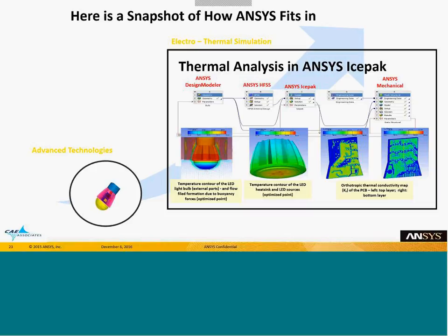Okay, so this was a very non-trivial simulation that we had to do, pulling all our physics together, and we used a platform that we call Workbench. We brought in the geometry. We had to design the antenna element. We used the HFSS design. We had to be cognizant of how the air was flowing inside the unit, inside the housing of that light bulb, as well as the airflow in the room that it was placed in, because not every room is air conditioned, or it could be heated up, and there are different environments. We have to be cognizant of airflow, or even location, because this happens to be in an industrial application, and there was an HVAC system there. So there's also noise and vibration that is included.